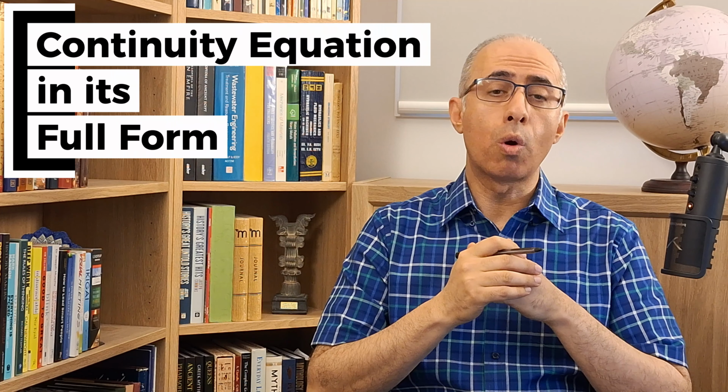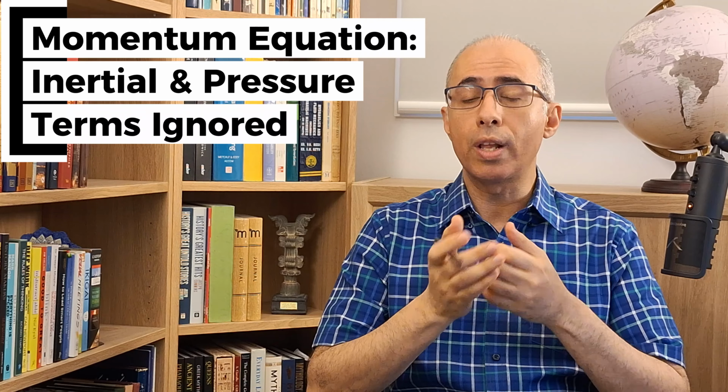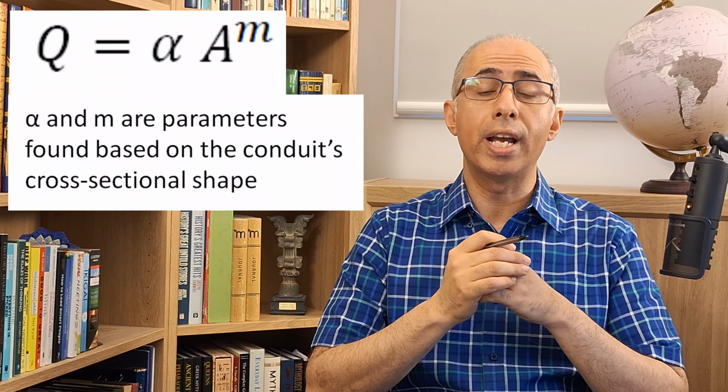The kinematic wave equation is derived by retaining the continuity equation in its full form, but simplifying the momentum equation by neglecting the inertial and pressure terms. It assumes a balance between gravity and friction forces and uses Manning's equation to express flow rate Q as a function of cross-sectional area A. Substituting this relationship into the continuity equation yields the kinematic wave equation.